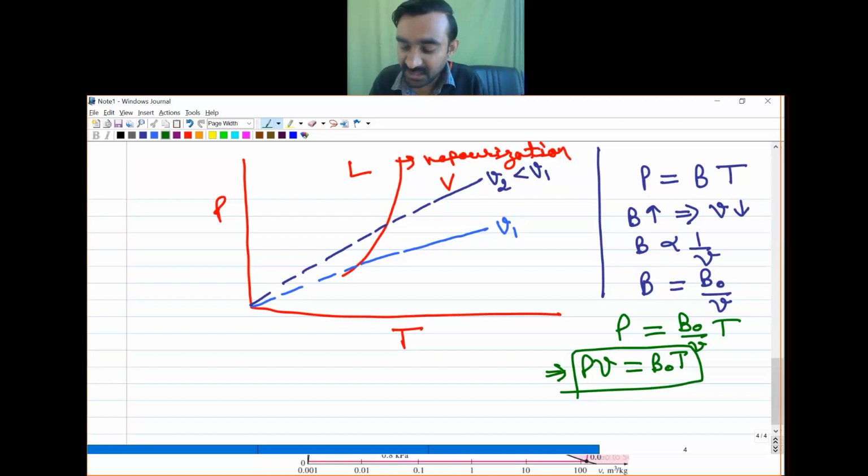So it means that irrespective of the property diagram, this is the generic nature of the substance: if we go to the superheated region, the ideal gas relationship is applicable, or I can say the equation of state identical to that of the ideal gas equation is applicable for water also, particularly in the superheated region. But I have already told you that this assumption is only applicable for a limited condition. The limited condition is low pressure and high temperature.